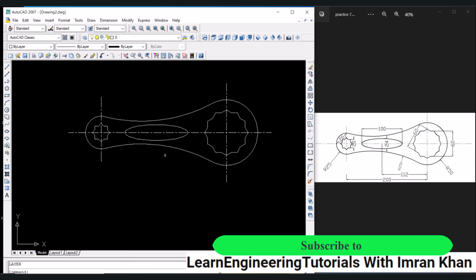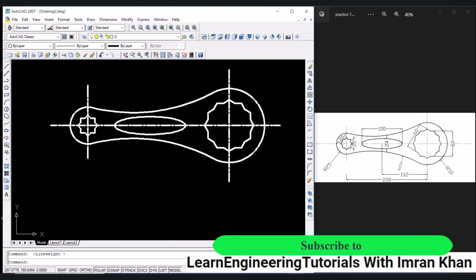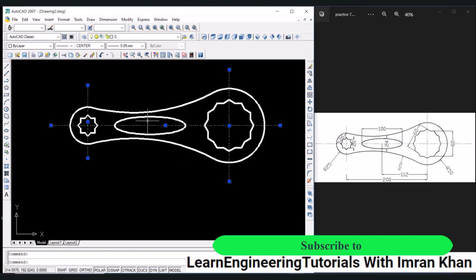Now in order to visualize the line type changes, for that let us turn on this LWT option. Now we can see that the formatting has been applied. Again, click on these lines, the center lines should be thin lines, so click on the line weight option, and here we can select 0.09, press escape. Now we have to perform dimensioning.